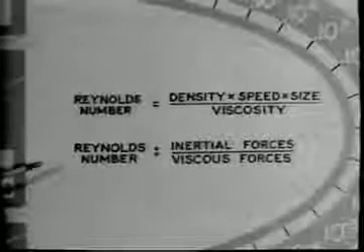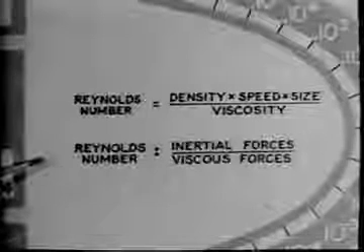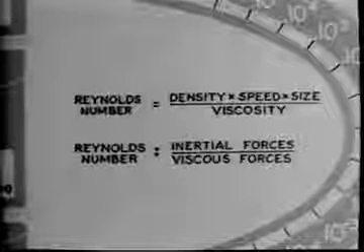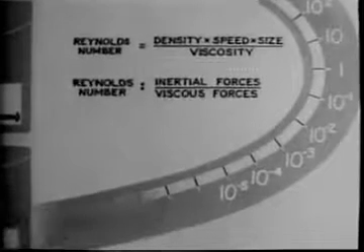The Reynolds number shows us something else, for it is a measure of the ratio of the inertial forces to the viscous forces in the force balance. A very, very low Reynolds number, for example, means that the viscous forces are so large compared with the inertial forces that the inertial forces may be neglected. We then have a balance between the net pressure force pushing on the fluid and the net viscous force resisting